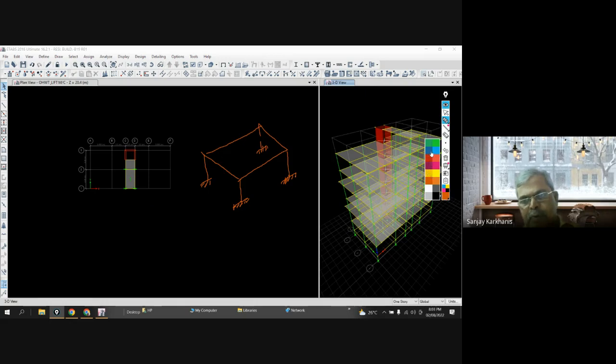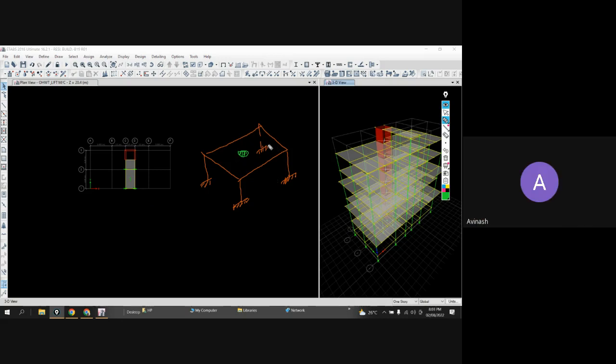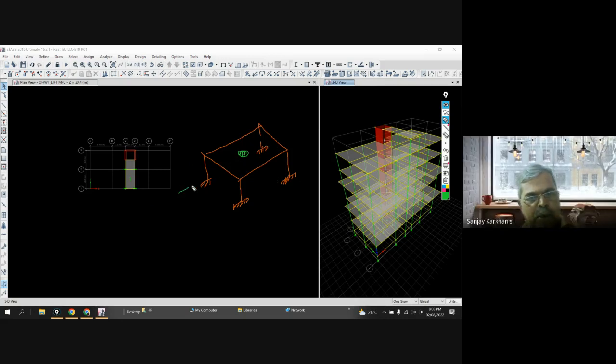So what you said is that instead of this you are going to consider mass over here, right? And the force will be applied due to earthquake in X direction like this, and you will find this mass something like this. So this leg consists of the equivalent of all these 4 columns, and it will vibrate like this. Okay, but actually you have the entire mass something like this.